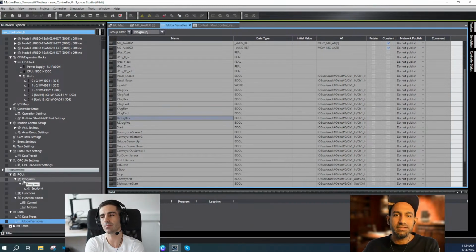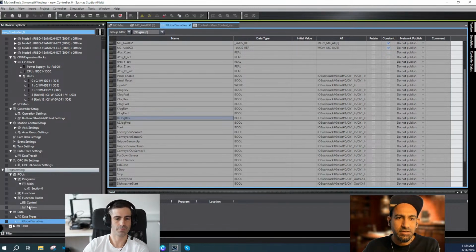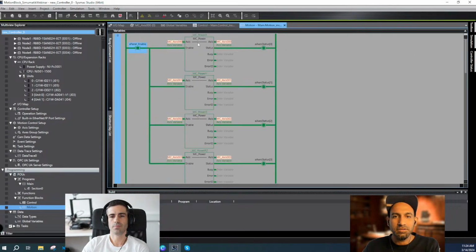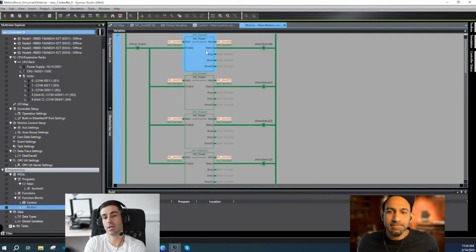Yeah, that's what I did. Because if you see another block, control block, or motion block. In the motion block, I had to create blocks in ladder logic, so I couldn't copy paste. I have to do it individually. It's just an example. If you make it in ladder diagram or FBD, you have to do it again in a different PLC. If it's structured text, you can easily copy paste, and it makes your work easy.